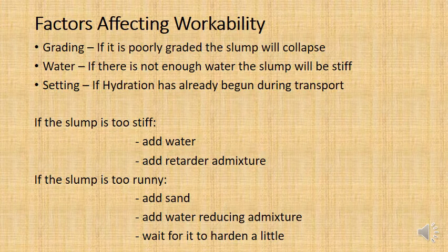So what are some of the factors which affect workability, which will determine whether your concrete is very stiff or if it's very runny? Well, one of the big ones is actually the grading of the aggregate. Remember how I said it was very important that the aggregate for concrete is very well graded or gap graded, and that's needed for strength as well as economy.